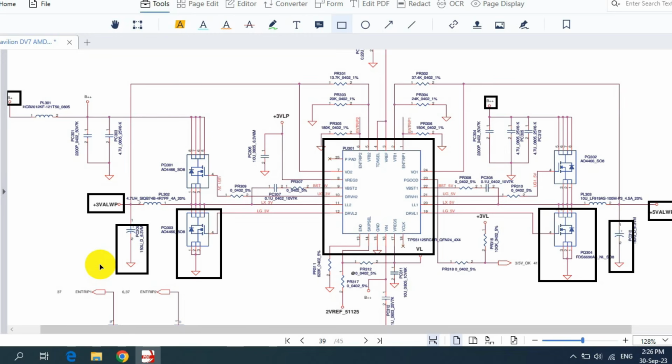And of course, you should always check the protection components, for example diodes in the circuit. You should check diodes, especially the diodes that are connected to the ground. Check also MOSFETs and capacitors. So this is basically the main thing about common faults in the motherboard.